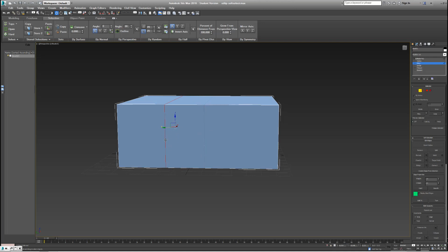And I realized that, okay, if I just punch this square out, that's a pretty big gap for a window or for a door. Maybe I need to chamfer this line a bit, to create more segments so I can make a smaller window. So I've just hit the Q key, which gets me back to the normal selection level. And I'm actually going to go in here to this icon next to chamfer. Chamfer, you can think of as a word for splitting things into 2 or more pieces. So a chamfer is going to basically split this line and clone it.